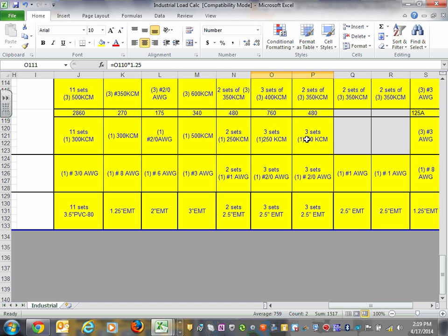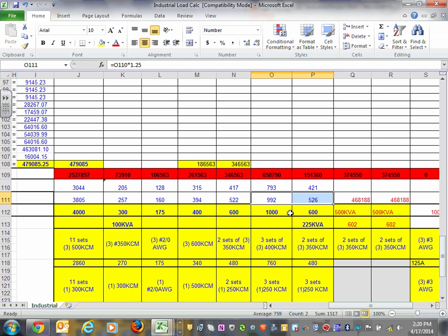So it's really cool. Bus duct, because where are you going to find the actual bus ducts? You can go to Square D, Cutler-Hammer, multiple manufacturers. Those guys have the actual bus duct sizes, industry standard. So the size is based on this number. If anybody's wondering, I came up with a bus duct and the overcurrent protection device. This also has to match the overcurrent protection device ahead of it. So I have 1,000 amp and 600 amp. And these happen to match what they use. But in reality, I want to warn you, you are sizing the overcurrent protection device.